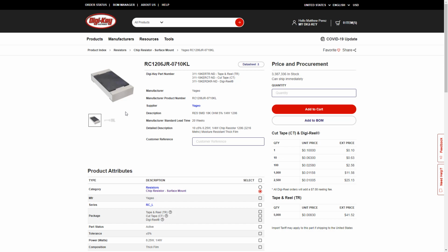This is especially true when you get into components like an SD card slot. The pin layout might be reversed or the pad layout might have keep out regions. So it's always a good idea to make sure that you at the very least double check the components you're ordering to make sure that their ideal pad layout is the same.